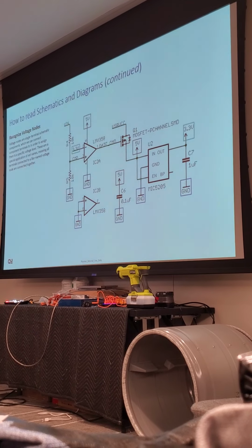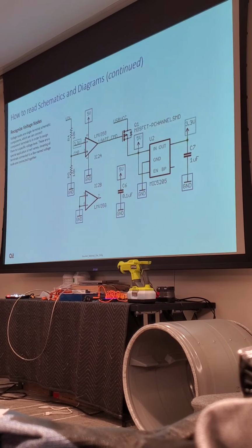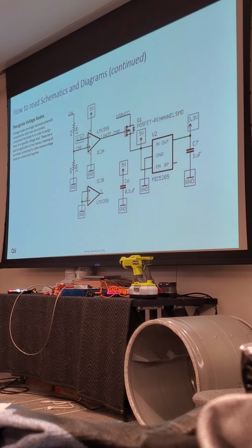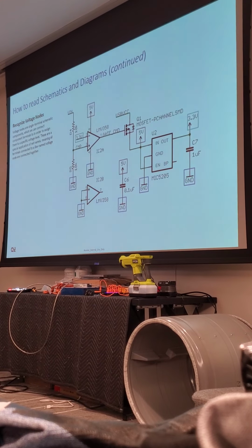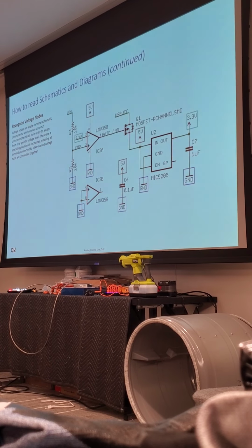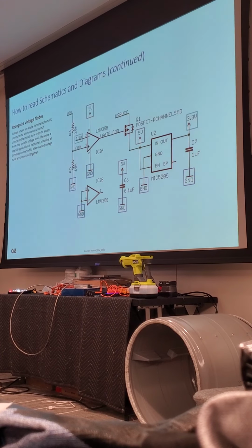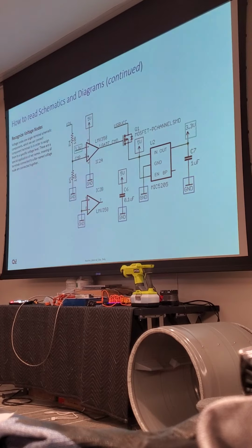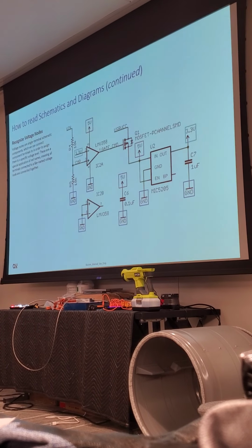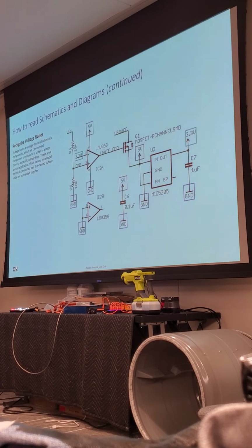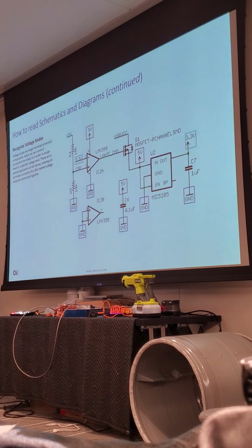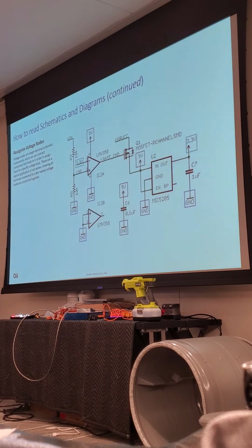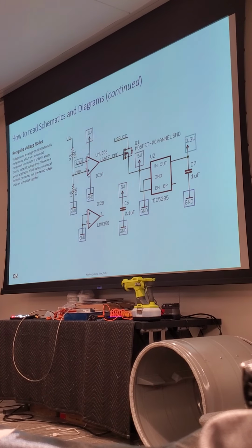Or if it's on CN76, you're going to go from pin 1 to pin 3 for your fresh food fan, but then you're going to go from pin 1 to pin 7 for your feedback. Okay? You really need to know this stuff like I do. You'll get it down when you go over it a lot of times. You keep doing it. It'll become second nature to you. You go in and say, oh, that's CN76, I need here and here. You get that familiar with what you're doing with more time.